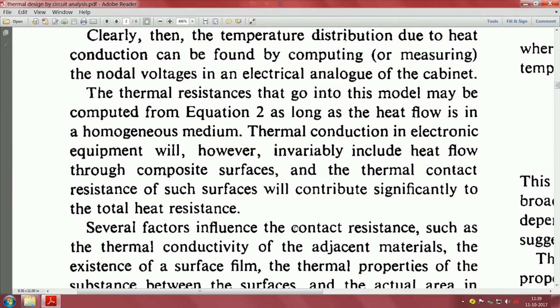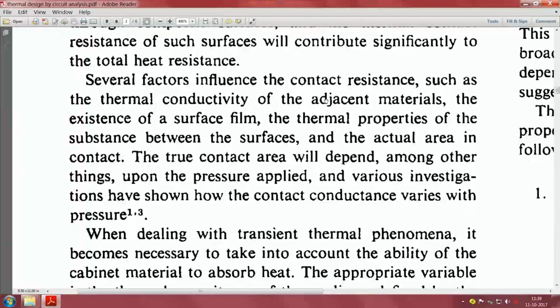This is where strictly adhering to specified physical mechanical parameters matters, like the Ra, the root mean square average of the pits and valleys, and also how well you protect it, and even movement between the fabrication shop and this.